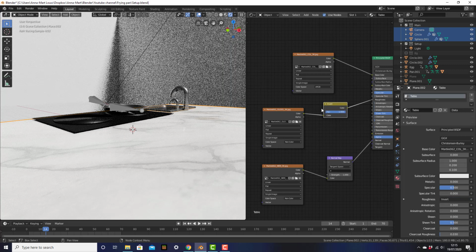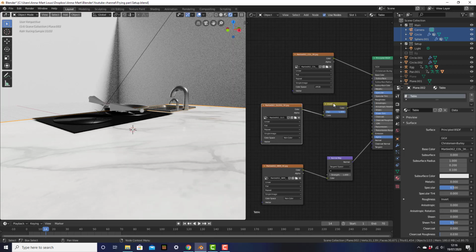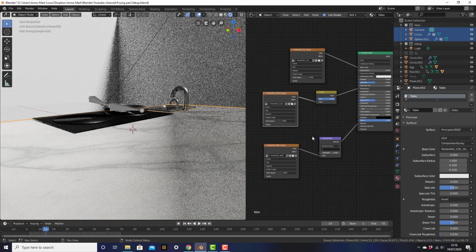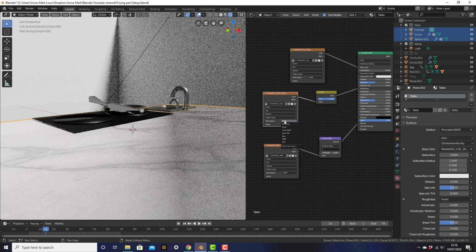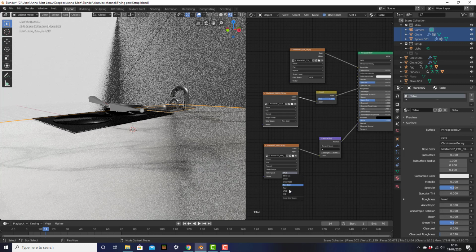Then you can select that and put it in between these. So when you have a map, it has black and white colors on it. And the white will represent the roughness or the smoothness of it, and the black will represent the other one. In a glossy map, the white is the smoothness, and in a roughness map, the white is the roughness. So if we just add a glossy map and invert the colors, then it will act as a roughness map. That's all we need to do for this. Just remember to change this sRGB to non-color on both the glossy and the normal map.